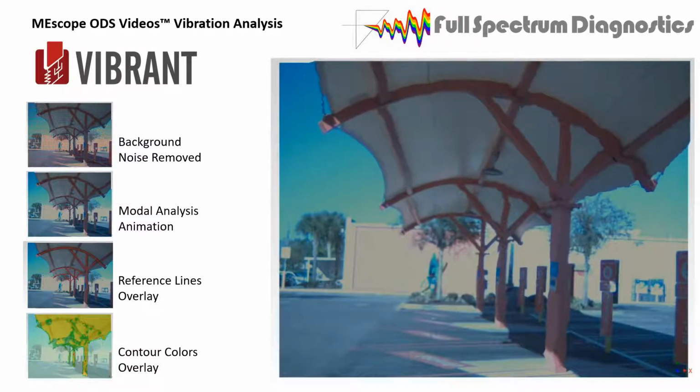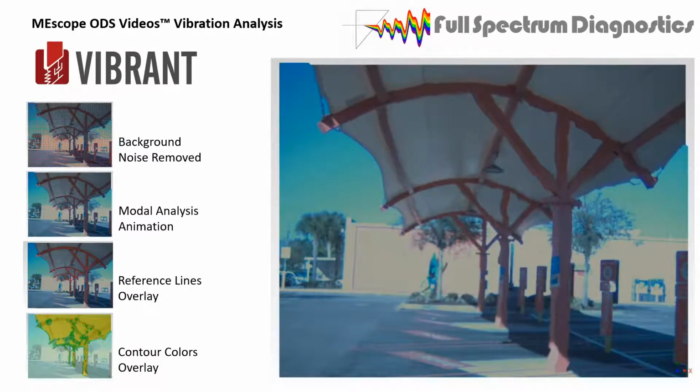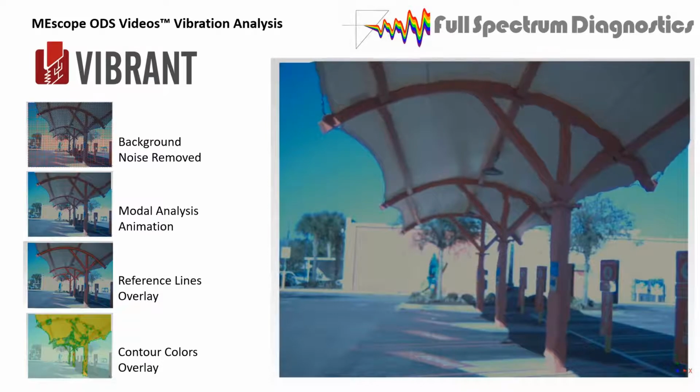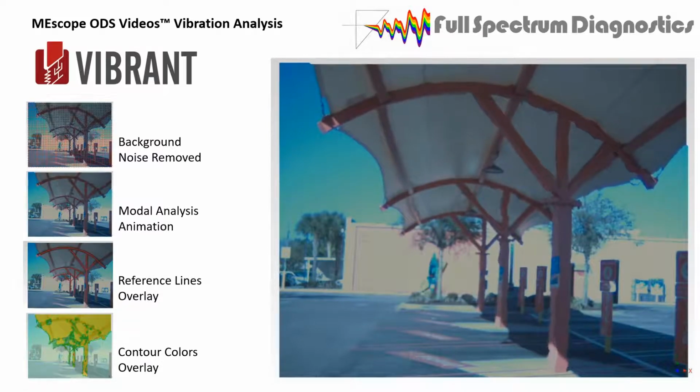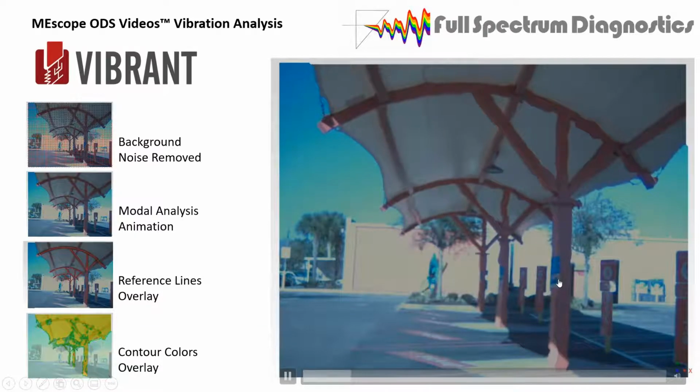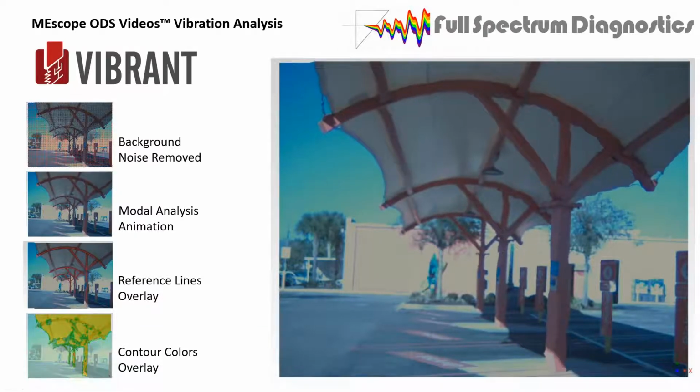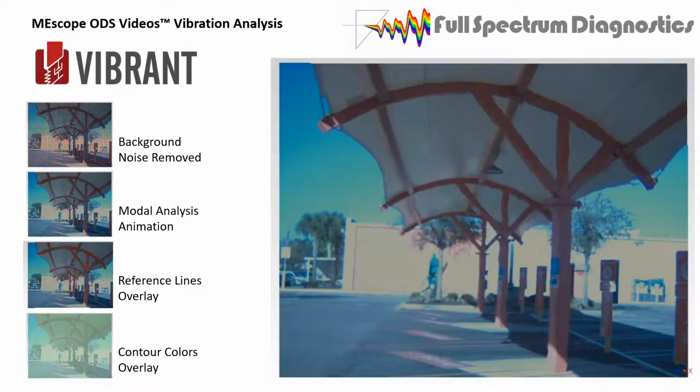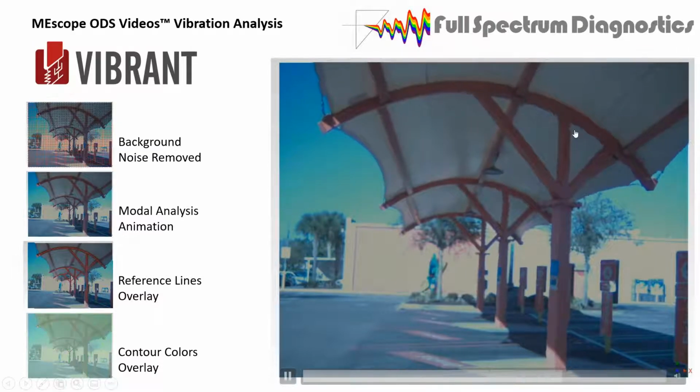And here it is without the dots used for reference. You can see all three beams are flexing. And this frame's beams are off center with respect to the carport structure. It's larger on the outboard side here. So you would expect a bending mode and twisting in this structure here.